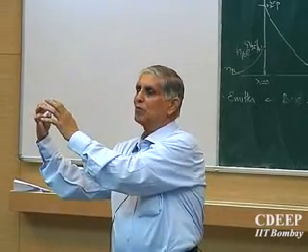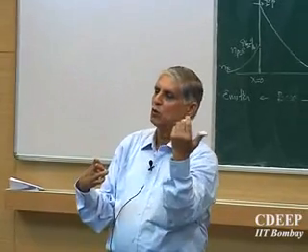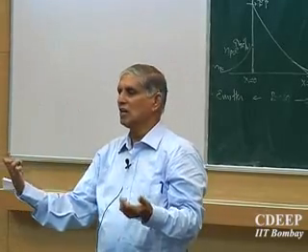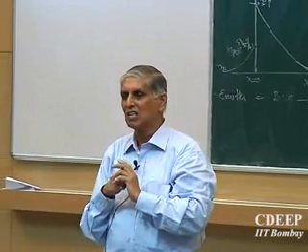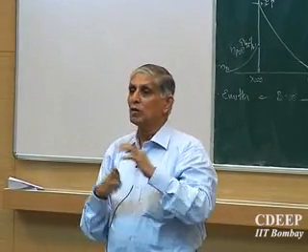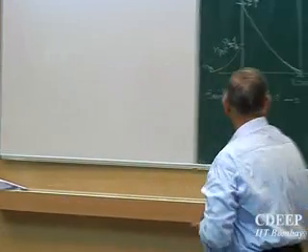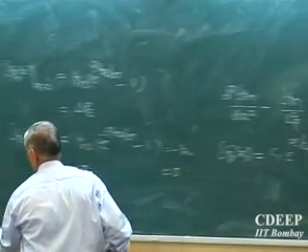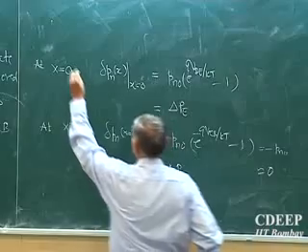If the emitter becomes the collector and the collector becomes the emitter, I say it's an inverse mode of operation. This will be the collector current, this will be my emitter current. So I want to keep the delta terms as they are. Biasing will decide whether it is forward bias values or reverse bias values. Once I know these two equations, two boundary conditions, these are two boundary conditions.